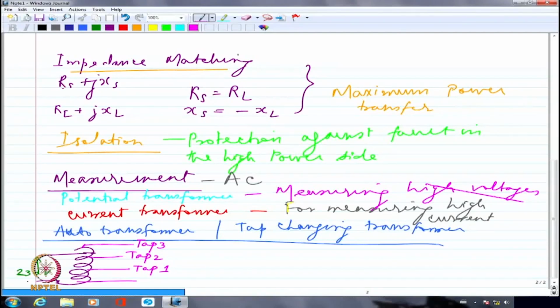So I would say the voltage at the terminal of the generator will be 400 kV minus whatever is my R plus jX of the transformer and generator multiplied by the current. Of course, I have to include the power factor angle, no doubt. This is how I am going to get the terminal voltage.